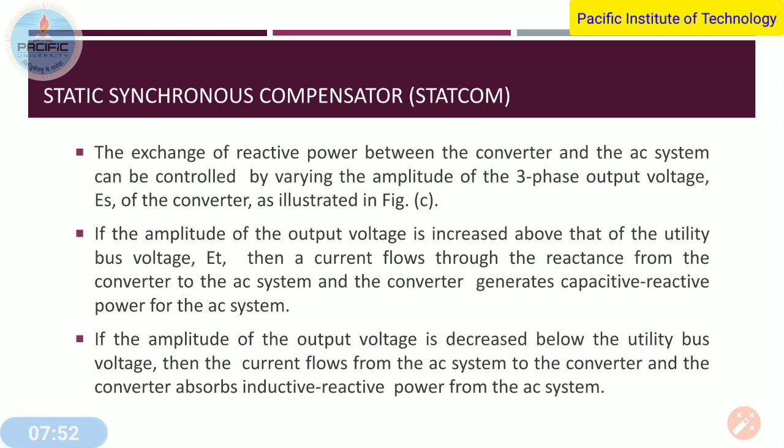So it all depends upon the STATCOM output voltage, whether it is greater than the system or utility voltage, or it is low compared to the system or utility voltage. So if it is greater than the utility voltage, then it will produce capacitive reactive power, and if it is lower than the utility voltage, then it will consume inductive reactive power.